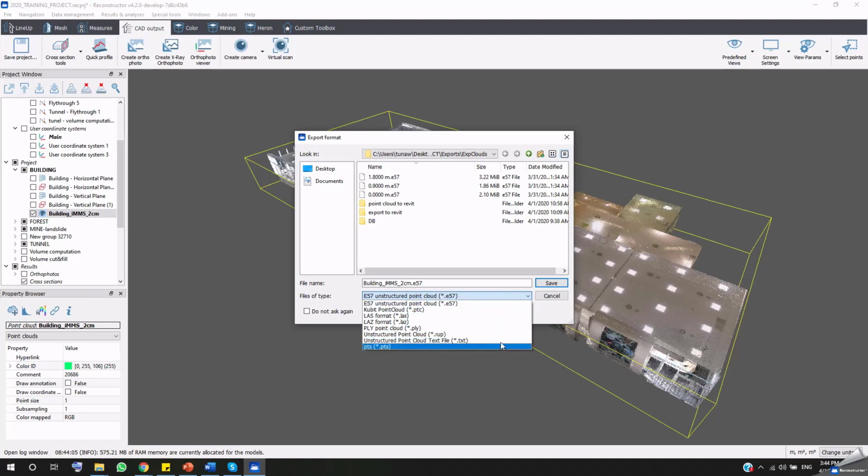I'd like to move to EdgeWise with a point cloud acquired by Aeron, the JAXA portable mobile mapping system. As you know, mobile mapping data are usually unstructured clouds, so you can export them in E57, PTS or XYZ. The one I suggest is the E57. Select it and move on.